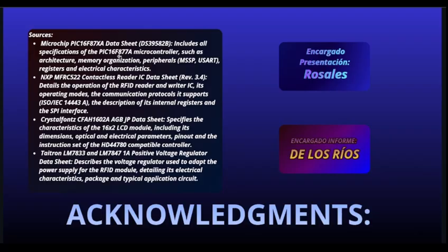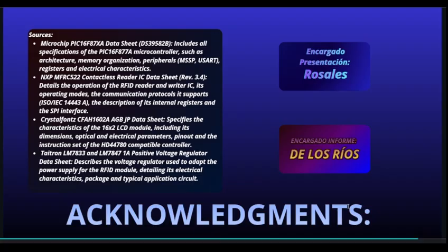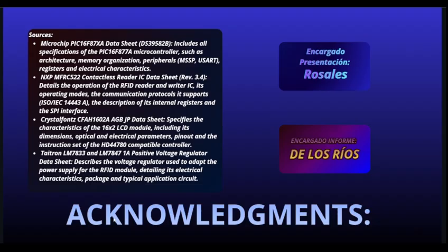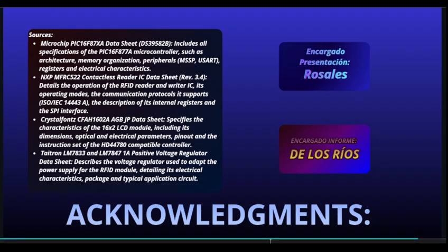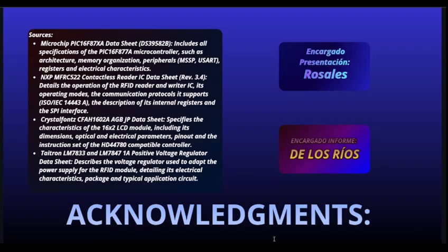NXP MFRC522 contactless reader IC datasheet, revision 3.4, details the operation of the RFID reader and writer IC, its operating modes, the communication protocols it supports, ISO/IEC 14443A, a description of its internal registers, and the SPI interface.